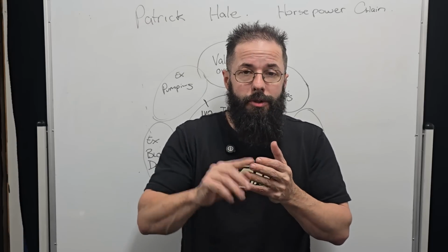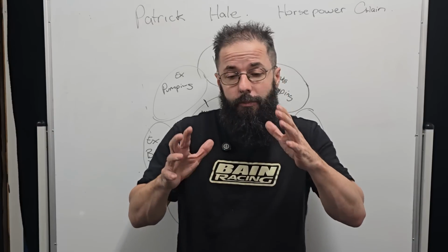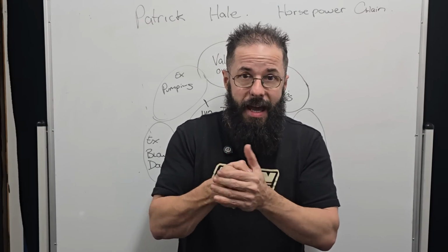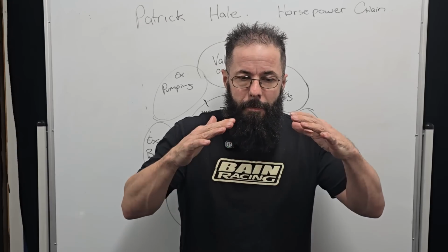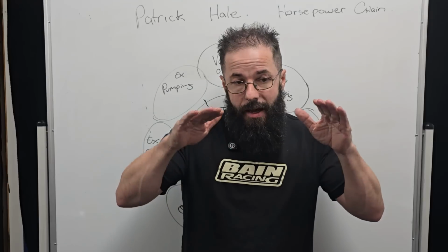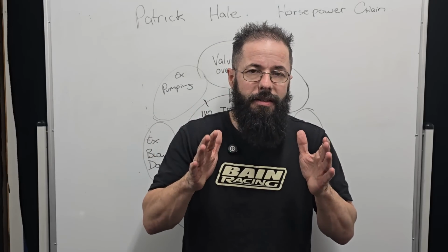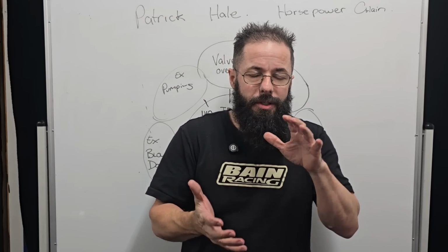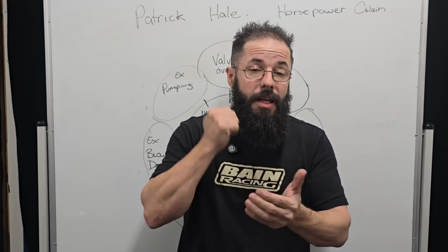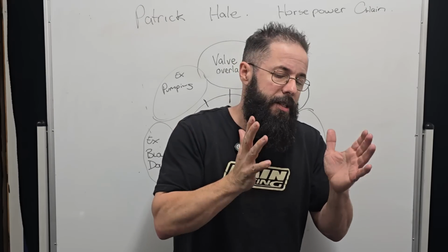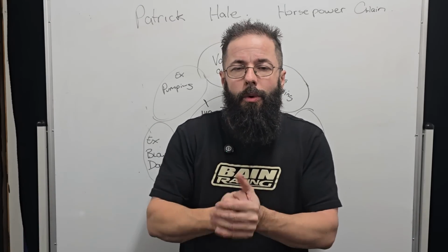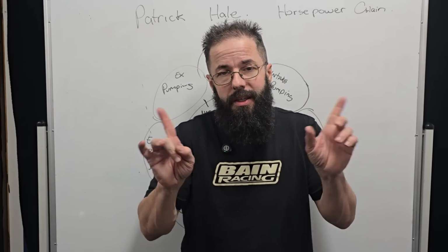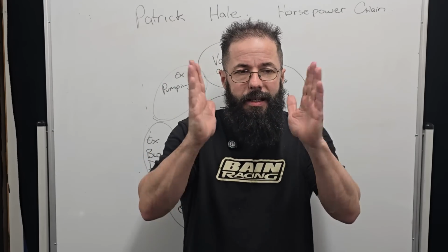The boost thresholds are lower because, again, remember, the turbo is driven by X amount of force coming out of the cylinder, X amount of bang. We need to create that. So the LSA affects that, but also the dynamic compression affects that, because the more duration we have that closed, the higher the cylinder pressure is going to be, the bigger the bang, the more gas that goes out and hits that turbine and turns it up. That's why a 10-to-1 engine, exactly the same, everything will boost sooner than an 8-to-1 engine. That should be obvious. So this is where the dynamic factor and LSA all come into it.